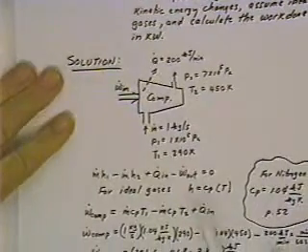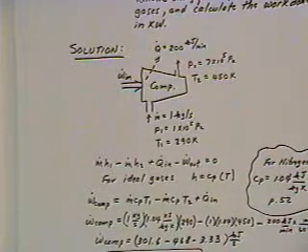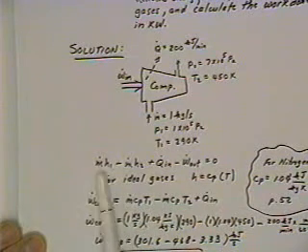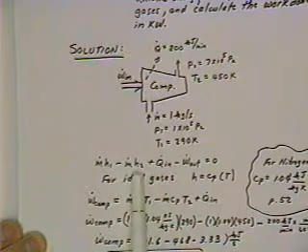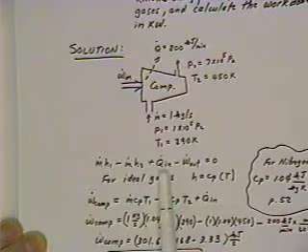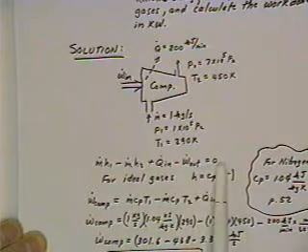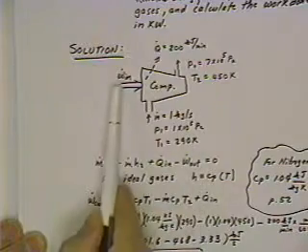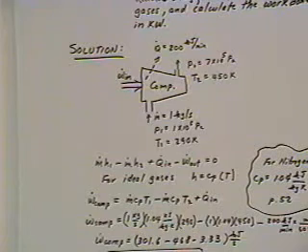450 degrees Kelvin. All right, so if we go down to our first law as a rate equation, we are neglecting the kinetic energy term, we're neglecting the potential energy term, so that leaves us with mass times enthalpy entering minus mass times enthalpy leaving, plus heat transfer into the system. In this particular case, we've got Q out of the system, so we know when we plug this in it's going to be negative, minus the work out for the system. And in this particular case, we know that we've got a work input, so we know that the work out term is also going to be negative.